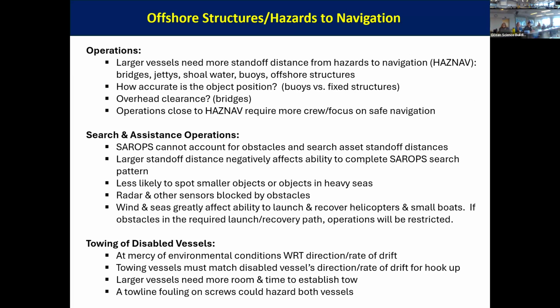Offshore, these are some of my notes as I was putting this together. Again, anytime you're thinking about ships, the larger the vessel, the more standoff distance you need from hazards. Anything, bridges, buoys, shoal water, we're going to need more distance from that because even if we think we're sitting still, the water is moving. And so we have to account for that. And even though you might think it's 4 knots, well, it might be 3.9, then it's 4.2, then it's 4.1. It's not static. So we want to give ourselves wiggle room.